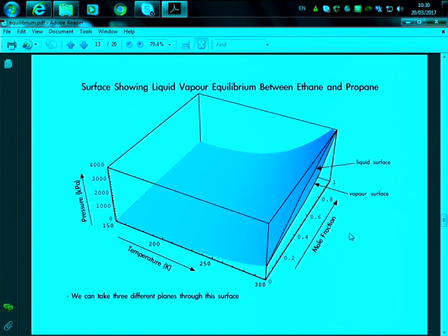So therefore, when the mixture of methanol and water reaches here, in liquid you will go down. In liquid, what do you contain? Methanol and water or only water? In a liquid, you will take out the methanol and water together, and here you will have a methanol-water fraction as well. But this fraction will be higher in terms of water than the fraction in the vapor. So with 73 you cannot evaporate the methanol.